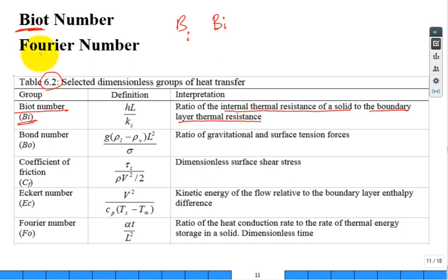There's another number we're going to use in this. So while we're in this table, let's go ahead and take a look at it. It's down here: Fourier. Hey, I've heard that name before. Have you heard the name Fourier before? Of course, in your math classes. And so here is the Fourier number, same individual, all that work in math. Is the O subscripted or not? Not subscripted, it's just 2 letters, Fo, Fourier number. Now, here's the definition, alpha t divided by L squared. What is alpha?